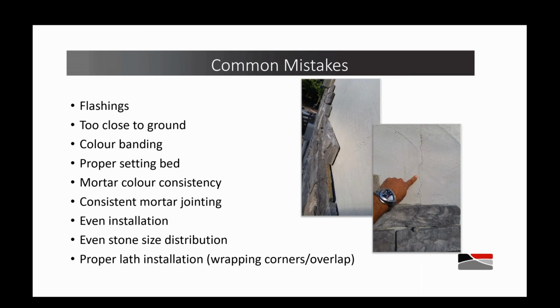And sometimes improper lath installation. You see, whenever you see cracking, like you see on the picture on the far right there, typically if you see that on a job site that you go to, and it's roughly at every point where the edge of a piece of lath would be, that's a pretty strong indication that they have not overlapped the lath correctly. And why that's important is if you get cracking in the scratch coat like that, there's a very good chance that you will get cracking in the stone as well. That can transfer through.